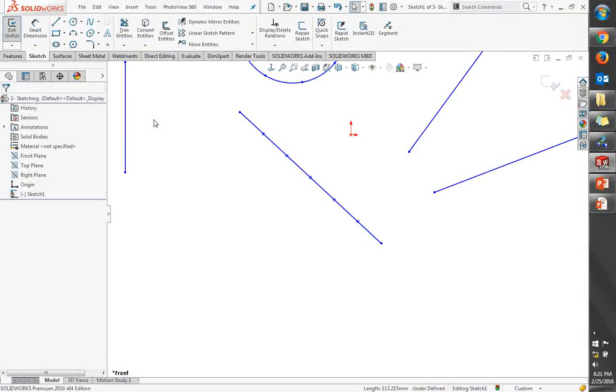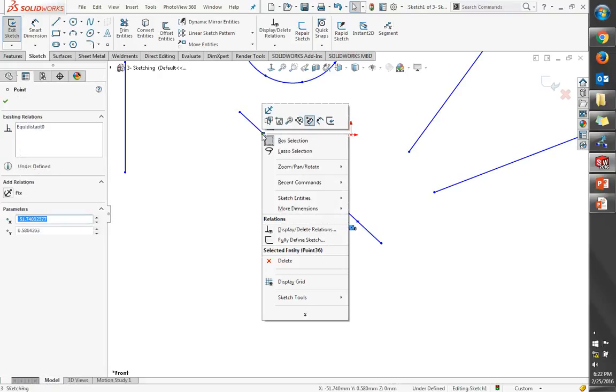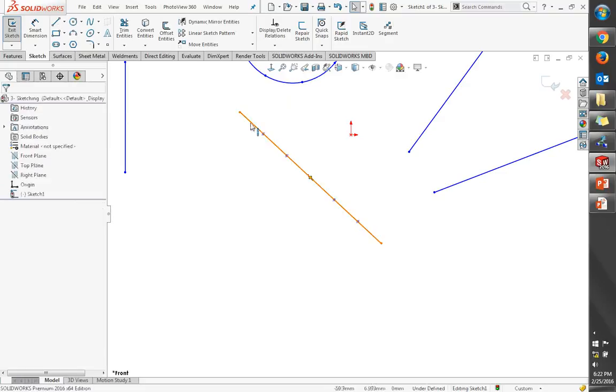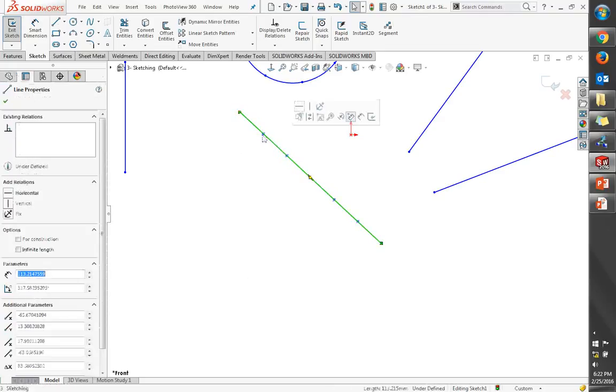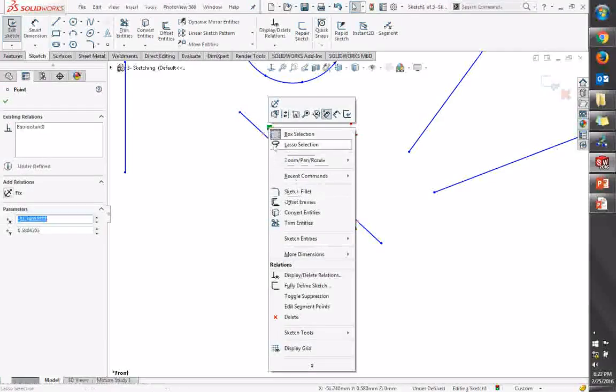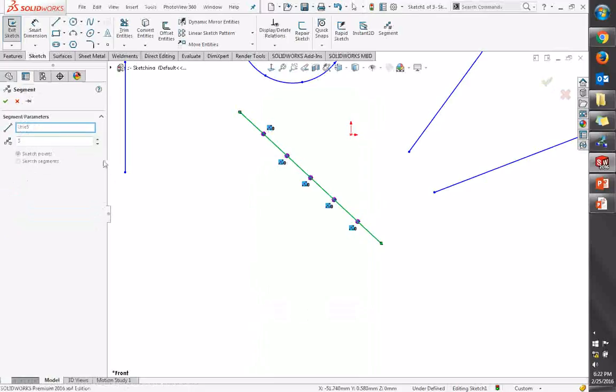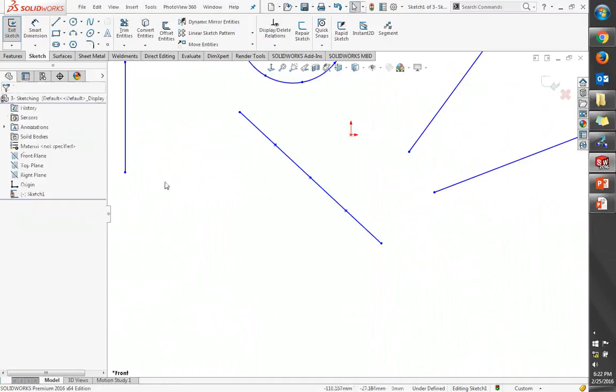So the sad part is that, well, let's check it out. If I get into it and I right-click on it, oh, where'd we put it? There we go. If you right-click on it, one more time, Ryan. You can do it. You got to right-click on the relationship. I apologize. Down here, you'll see the edit sketch or segment points. When you click on it, it will give you the options. It's almost like a feature inside of a sketch, similar to our pattern tool as well too. So if you need to adjust it, you can go ahead and adjust that as well too.